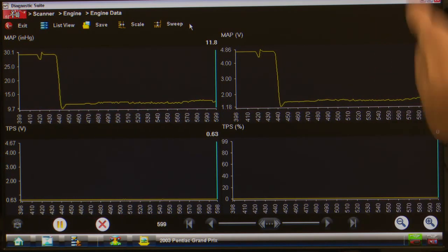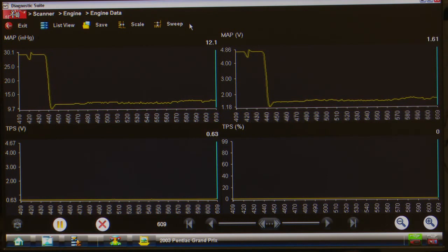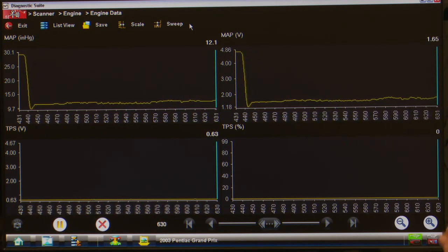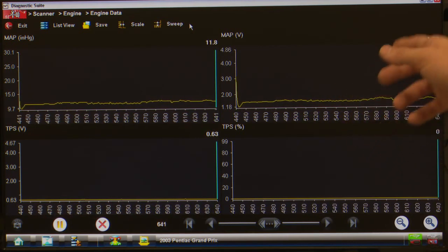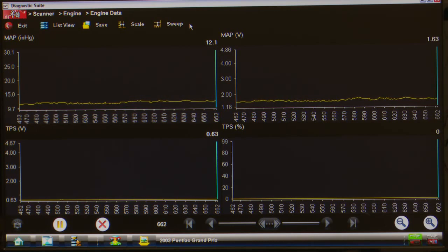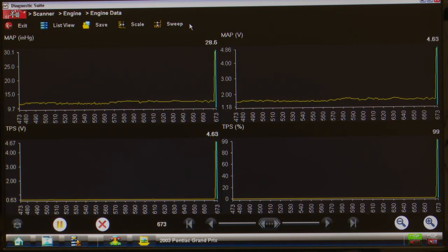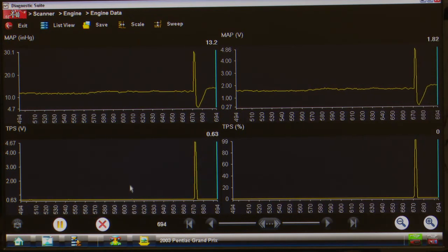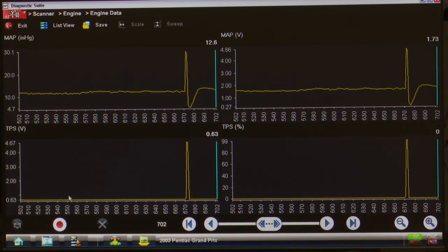But now if you close that throttle plate back to sealed up while the motor's spinning fast, it's actually going to draw more vacuum than it would at idle. So we're going to see it go up and then drop down and actually dip lower than our idle line. Go ahead and do that and let's show that. So there we go. I'm going to pause this. All right, you can shut it off. Just leave the key on.